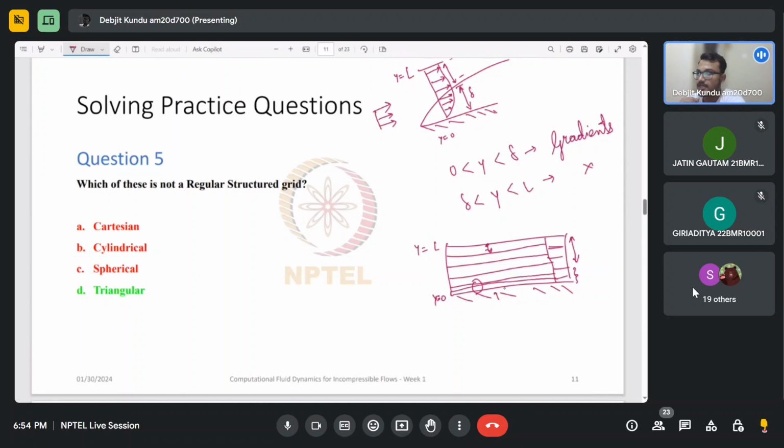Now here comes another thing. For this simple case, you know that there will be a boundary layer forming near the wall and there will be gradients in that boundary layer. So I refine that region. Now, if you're trying to model an entirely unknown system where you don't know where high gradients would be, what would you do then? So in that case, there is something called adaptive meshing.